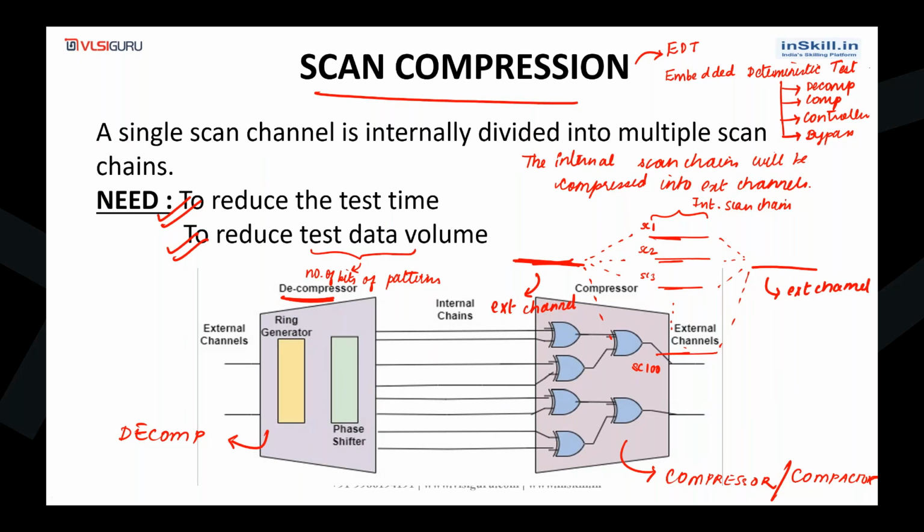So in order to achieve scan compression, if you're using the Mentor Graphics testing tool, you'll be adding a logic called EDT. The full form of EDT is embedded deterministic test.